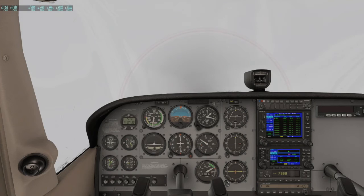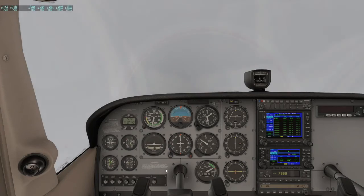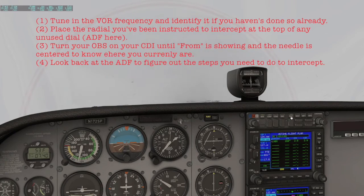And we're going to go ahead now and start doing some exercises. Okay, so first thing, let's say you've been instructed by ATC to intercept, for example, radial 300 inbound. First thing, you tune in and identify, as I've discussed before. That's the most important step that you have to start with. You tune in the frequency of your VOR station, which is here 117.1, and then you listen to the Morse code of the frequency in your aircraft to make sure that it's operational.